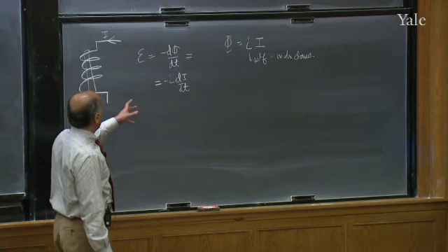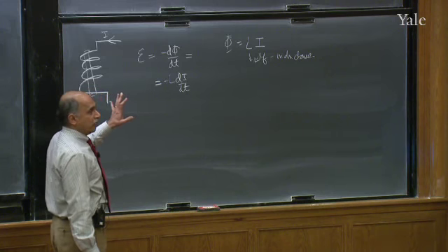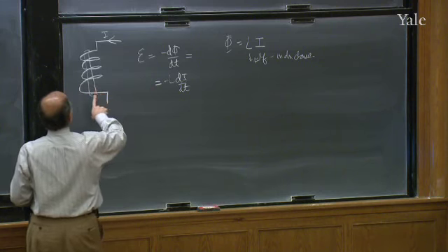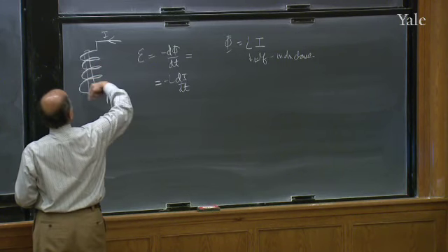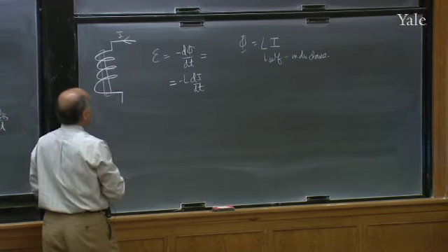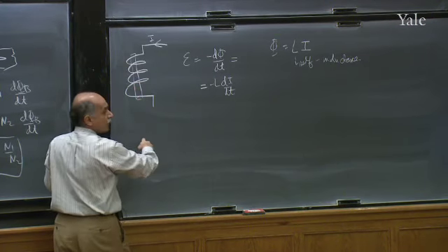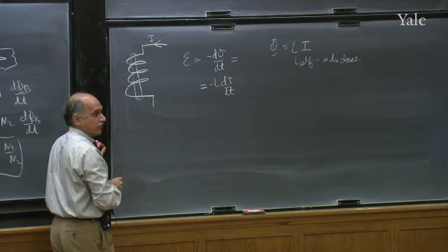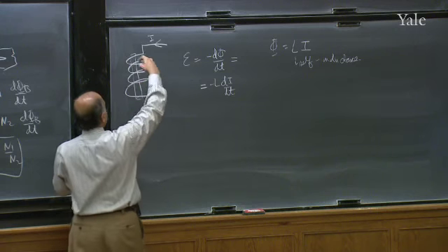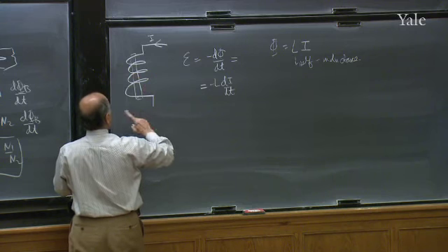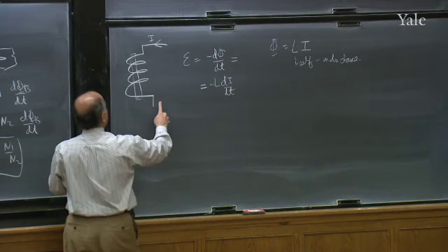We will calculate L in a moment, but I'm just telling you that as long as di/dt is not 0, you will have to oppose the back EMF with a voltage from some other supply. So in this example, if the current is trying to increase, then a back EMF will be set up to fight it.